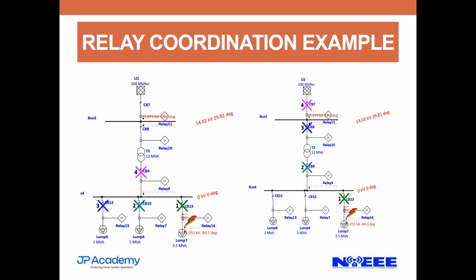So comparing the two diagrams, diagram 1 is still better because we still have a bus bar energized. But in the case of the second diagram, the bus bar is lost, there is no power to the bus bar. So I will still pick diagram 1, though both of them, in terms of selectivity and protective coordination, are not good. But I still prefer diagram 1 to 2.